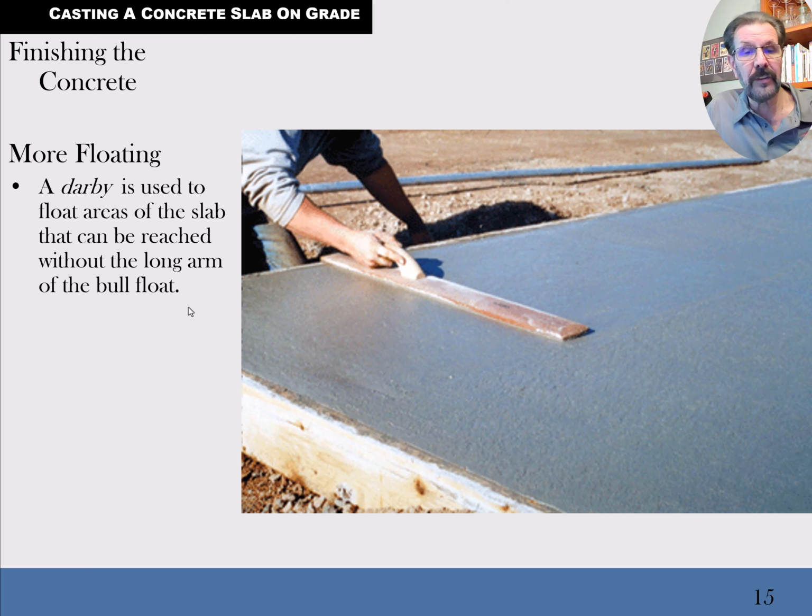So the idea is within the first 30 minutes or so after placing the concrete, you will get a lake of water that will come to the surface. Unless you don't have any plastic sheeting underneath, and it might get sucked up into the ground, and so you may not have as much free water then. But in the floating stage, you do it right after you've screeded, and you're working a few fines to the surface. It definitely is smoother, but you're also filling holes. You find holes, you might be taking a shovel full of concrete and placing it in there where there's a depression, trying to keep this thing as flat as possible.